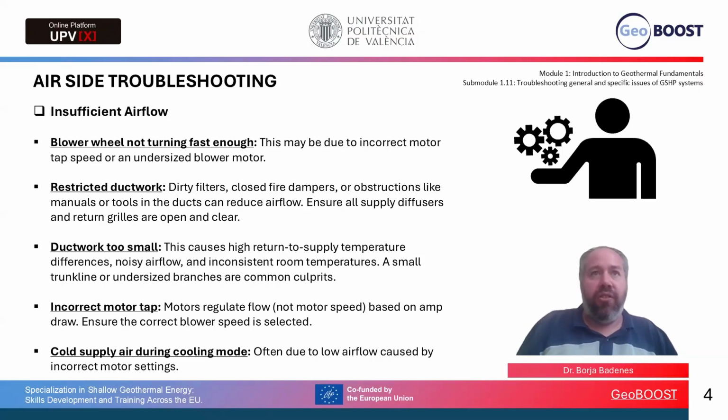The first part is the air side. When the airflow is too low, check these points. 1. The blower wheel. Is it turning fast enough? The motor tap speed or motor size may be wrong. 2. The ductwork. Are filters dirty? Are fire dampers closed? Are there any tools or boxes blocking the duct?